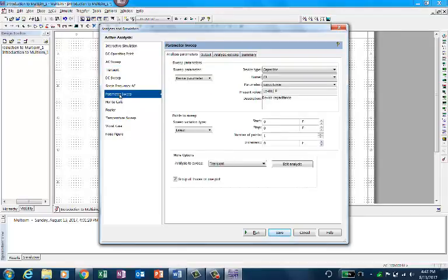You can define a parameter, like a capacitor is a parameter. You can sweep that parameter, and you can define a capacitor or a variable as a sweep. You can say the capacitor is a device, you can make it a variable, start from one value to the other values, and change it. Or you can put a resistor or an inductor or resistance R1, and vary its value starting from one value to the other value, and you can see the transient response of that. That's a very useful one. And what is the other one I was looking for?